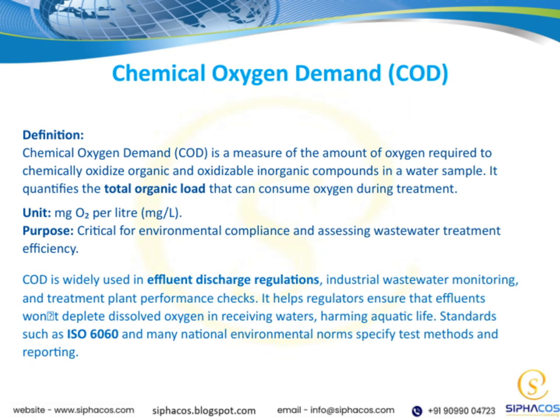Now, why is this important? Well, COD is critical for environmental compliance and for assessing how effective wastewater treatment processes are. It's a key parameter regulators look at to ensure that effluents won't deplete dissolved oxygen in receiving waters, which is vital for protecting aquatic life. You'll find COD being used in discharge regulations, industrial wastewater monitoring, and in checking how well treatment plants are performing. Standards like ISO 6060 and many national norms specify how to test for COD and how to report the results.